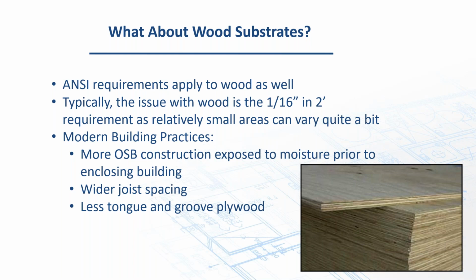Quite often we get OSB exposed to moisture. Maybe you live where Jim does up there in Minnesota, and they dump off a bunch of joists in the yard, and it sits there in the snow for a few months, and then they bring it in and start putting down their joists. That OSB is kind of like a sponge that we use in the tile industry. You put that sponge in your bucket of water and it's going to sit there and float on the top. But once you wring it out and let water get in there, you can take it on very easily every time after that. In other words, once OSB gets soaked, it expands and will allow moisture to get into it much, much easier. If it's kept dry, it'll hold up pretty well.